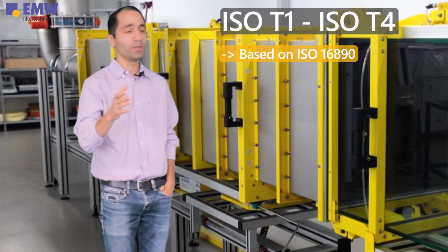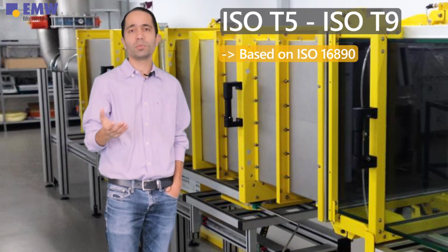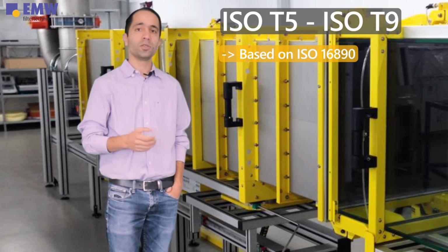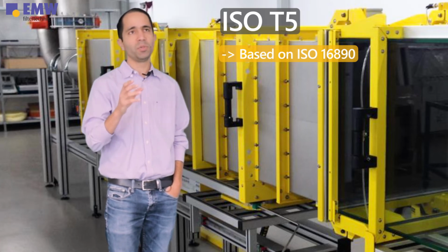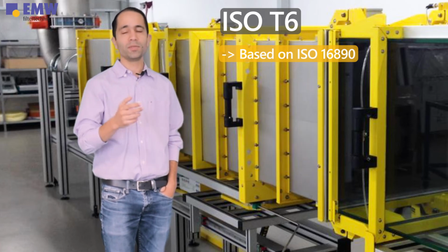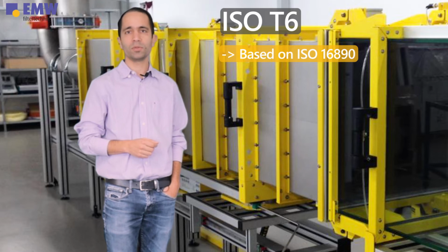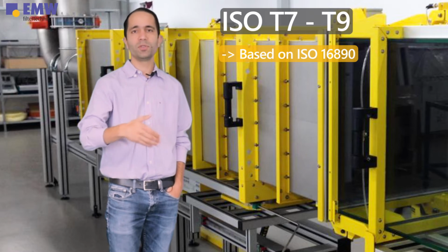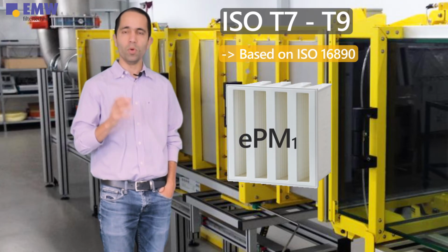So now, in the next step, we have a look at the filter classes T5 to T9, and there we still talk about the test procedure which is based on the existing test standard ISO 16890. In comparison, we could say that the T5 filter class pretty much deals in the particle spectrum of ISO ePM10, whereas the filter class T6 pretty much deals with the particle spectrum of ISO ePM2.5, and the higher filter classes T7 to T9 deal pretty much in the spectrum of ISO ePM1.